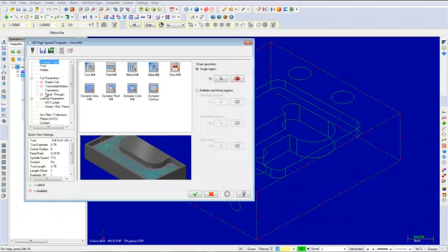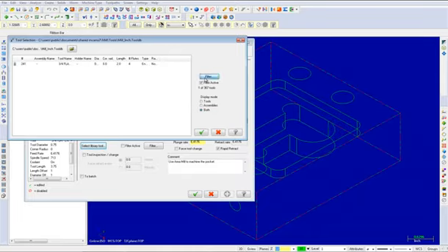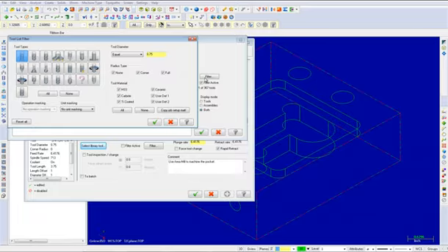Select Tool from the Tree View list. From here, click the Select Library Tool button and then choose the Filter button. Select the None button and then click under Tool Types and choose the Flat End Mill icon. Next, under Tool Diameter, pick Equal and input a value of 0.625. Once complete, select the OK button to exit the Tool List filter.